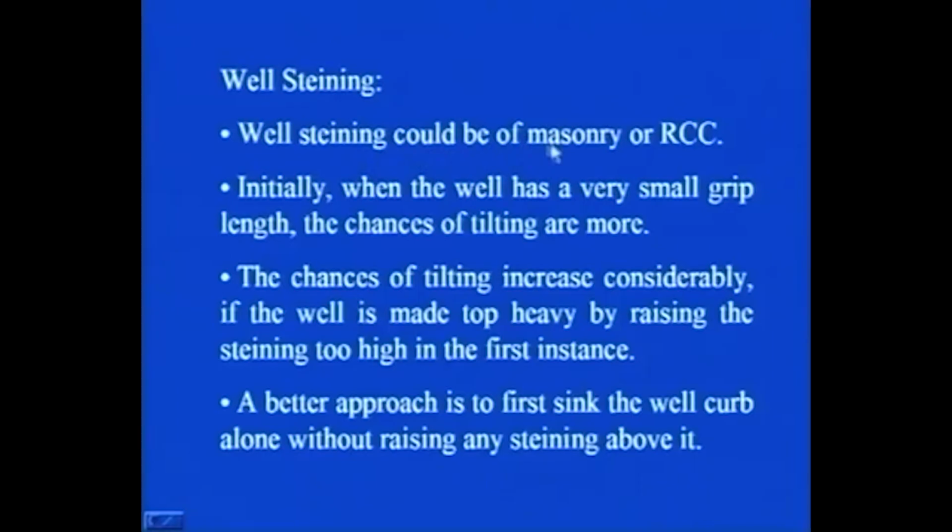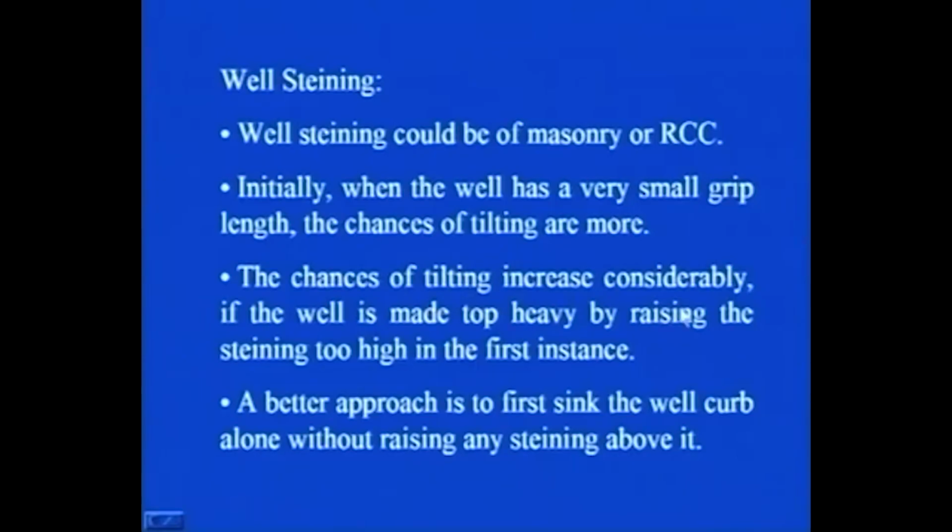Well steining could be of masonry or RCC. Initially, when the well has very small grip length, the chances of tilting are more. I told you that when you sink the well, the tilting and the shifting should be as little as possible and within permissible limits. When the well has very small grip length, the chances of the well steining getting tilted are quite high. The chances of tilting increase considerably if the well is made top heavy by raising the steining too high in the first instance. So, you have to keep in mind that in one go you do not raise the vertical well steining quite high.